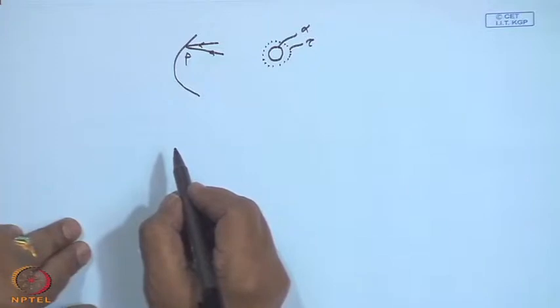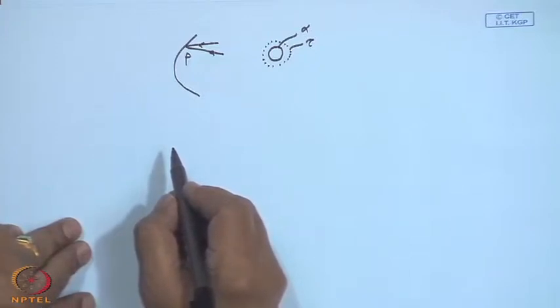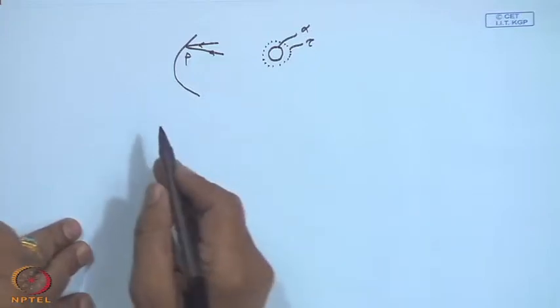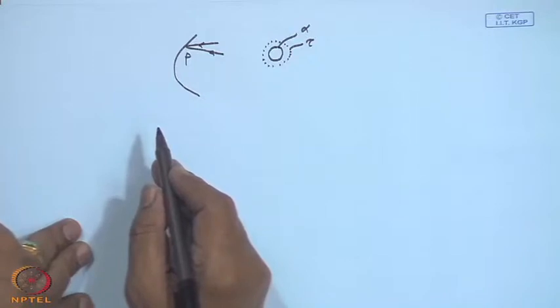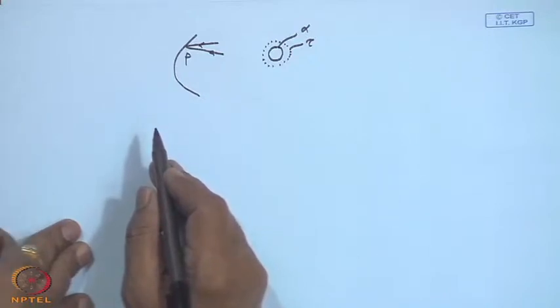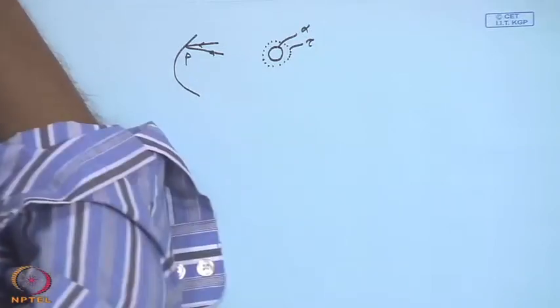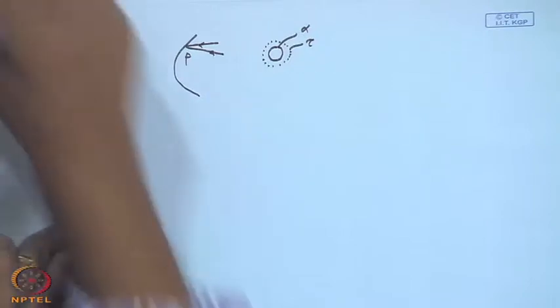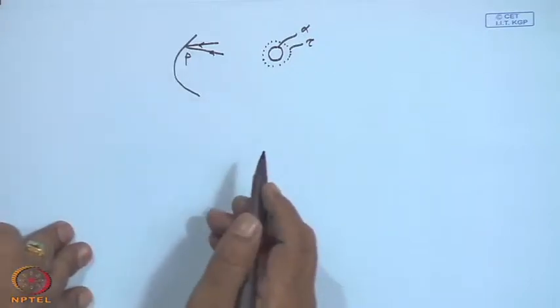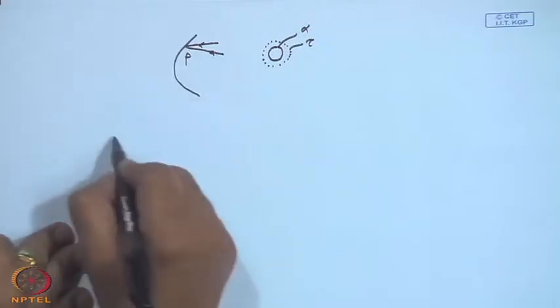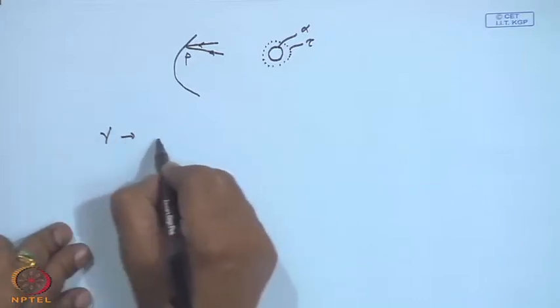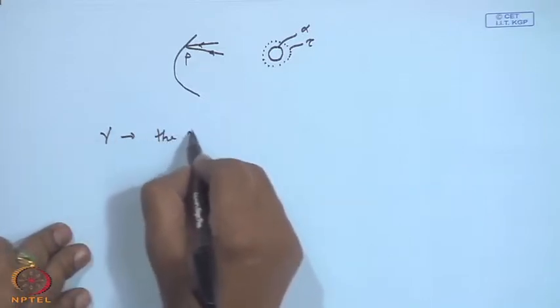Instead of just tau into alpha, we have a reflectivity of the reflector, or refractive index in the case of a refractor, the transmittance of the outer glass cover surrounding the tube, and the absorptivity alpha. There is another additional parameter, gamma, the interceptance factor.